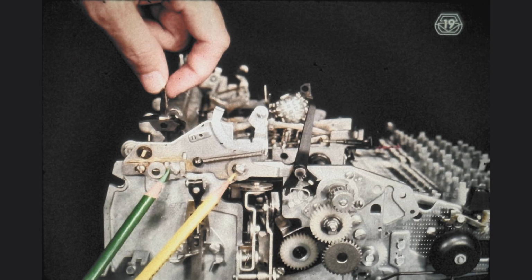In addition to being able to adjust the position of the platen front to rear, we must also be able to adjust it vertically. The platen height is controlled by the position of the brackets indicated by the yellow pencil. For example, whenever the ABC lever, or multiple copy control lever, is in position A, if a character prints too heavily on the top and too weakly on the bottom, the platen should be lowered so as to place more rubber, platen rubber, that is, behind the portion of the character which was printed too lightly.